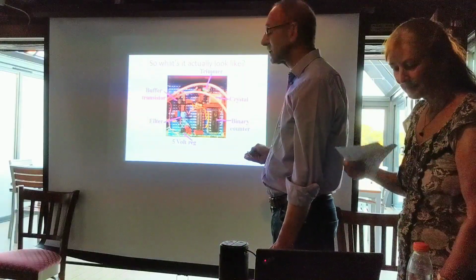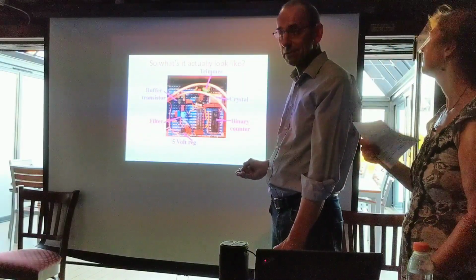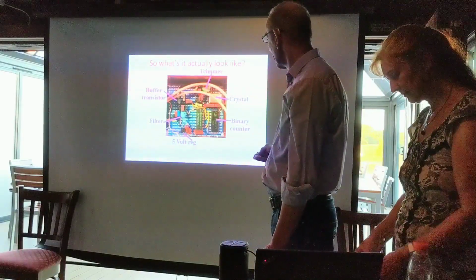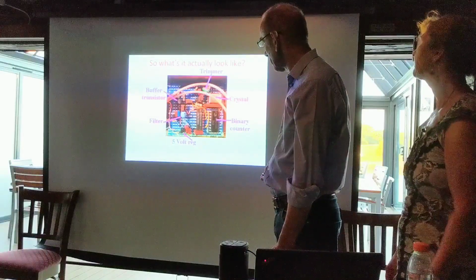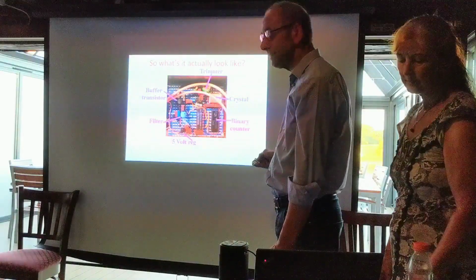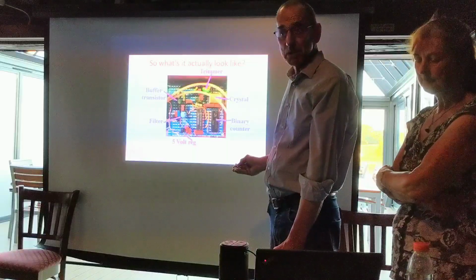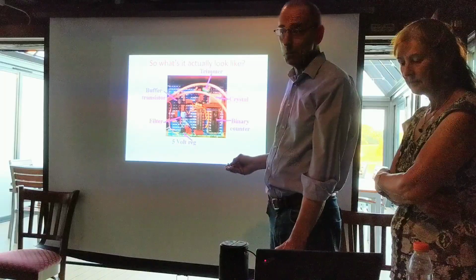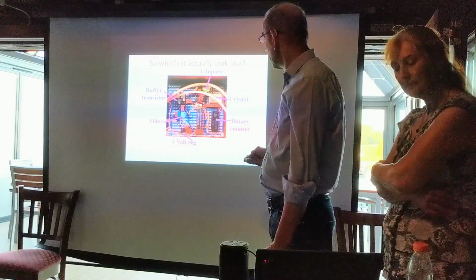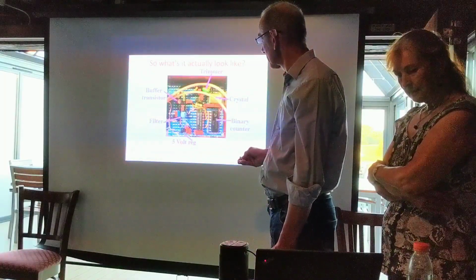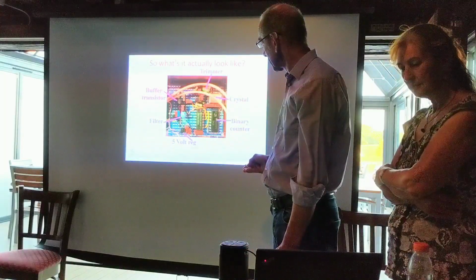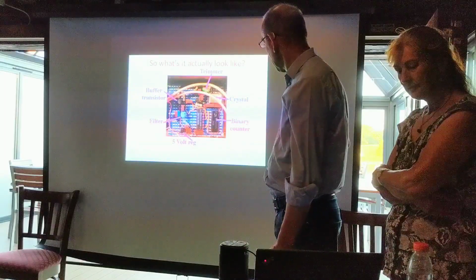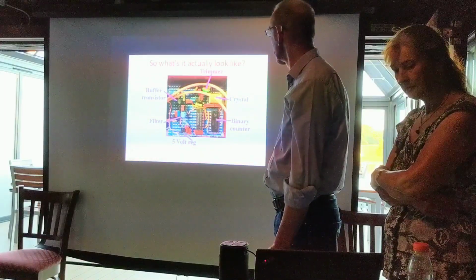Here's the crystal, here's a little trimmer, just to make sure it's absolutely spot on, because on the 472 kilohertz band you have to be pretty accurate. And this crystal has a 5 volt regulator. The stability of the crystal oscillator is much better if you can provide it with a really good supply. And obviously, if you're using WSPR, you do not want the frequency to wander about. That's the oscillator transistor, that's the buffer transistor, that's the little filter circuit, that's the inductor and some capacitors that generates the 3.2 megahertz bit, and that's the binary counter, the preset counter.